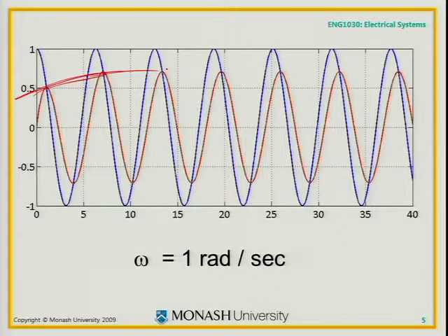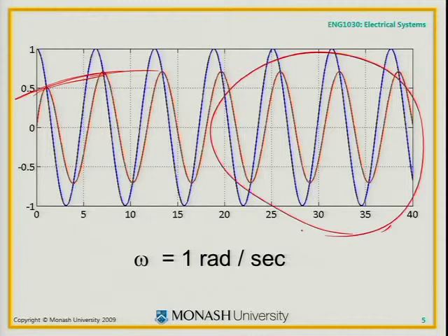That's some exponential transient. Exactly the same exponential transient with the same time constant that we would have got when the source was DC. That transient doesn't change. Okay, so there's still these exponential transients there. Whereas when we had a DC voltage source, the steady state was a DC value. With a sinusoidal driving function, the steady state up here is sinusoidal. So that's the first thing to notice. There is this transient still, but then there's the steady state, which is another sinusoid.